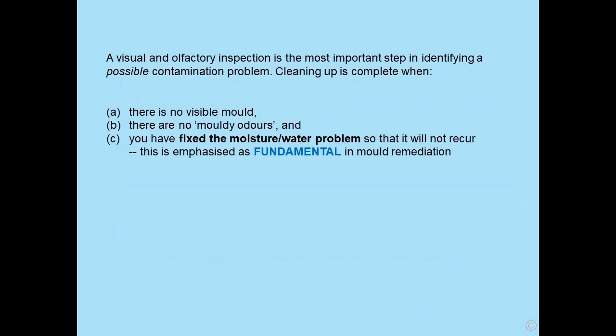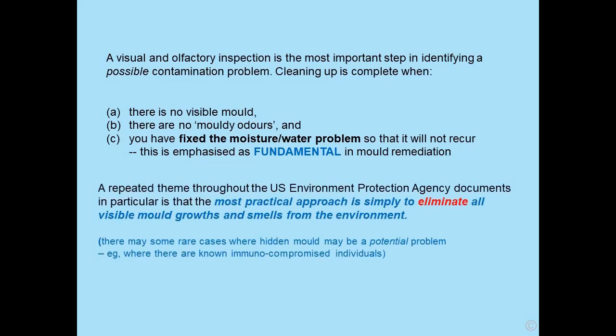And clean up, well, a visual and olfactory inspection is the most important step in identifying a possible contamination problem. Cleaning up is where there's no visible mould, no mouldy odours, and very important, you have fixed the moisture and water problem so that it will not recur. This is emphasised as fundamental in mould remediation.